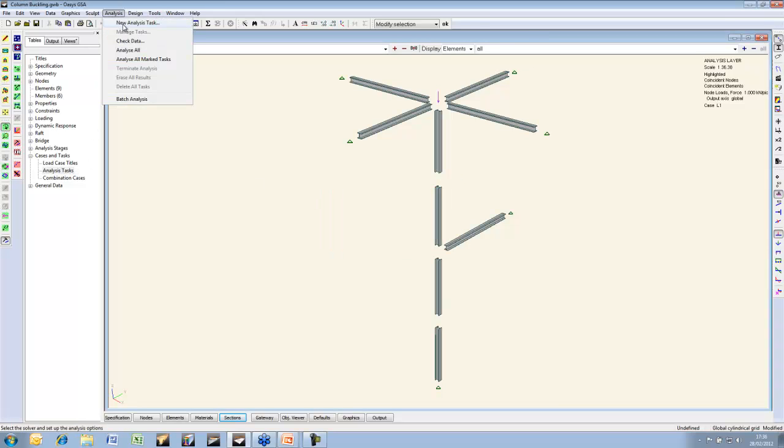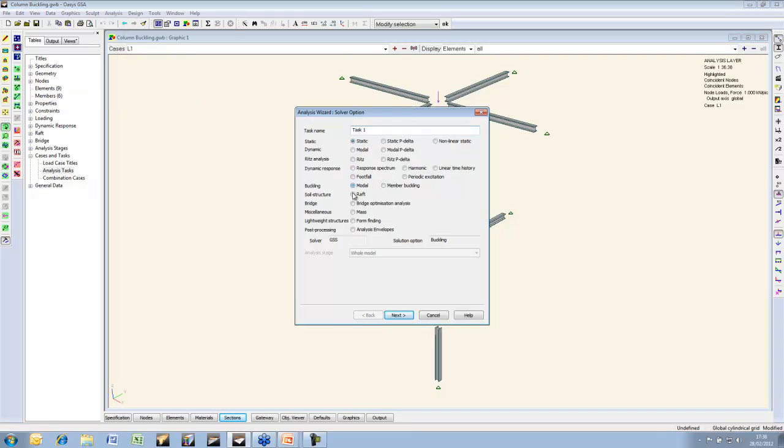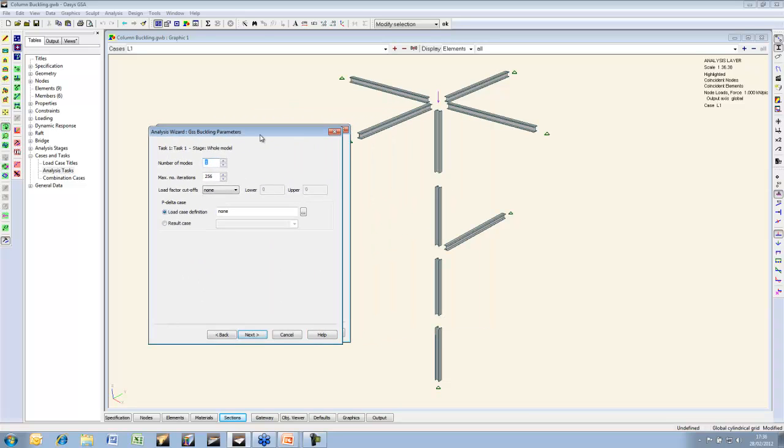What we can do is create a new modal buckling analysis. I'm just going to ask for 4 modes on this to begin with. It is an iterative method, so you might want to include a cut-off point if the analysis is going on too long. Load factors are interesting. As I mentioned, you're looking for axial loads where the stiffness goes to 0. Now if that load up there was a tension load, we would then get a negative load factor, which of course is nonsense. Tension loads don't buckle structures, only compression loads do.